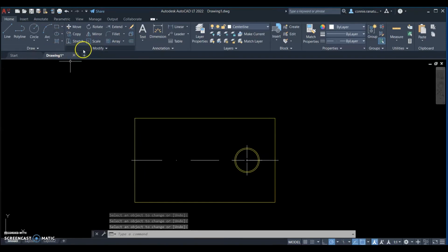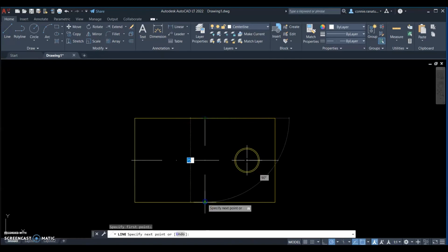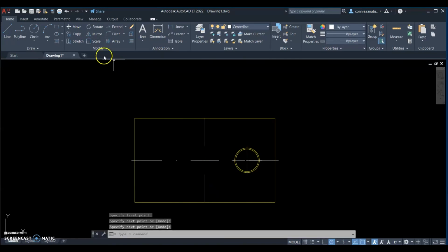So I can also do the same thing this way. I go to lengthen, I press delta. So now it already has 3 millimeters, so I just press enter and press the line enter.